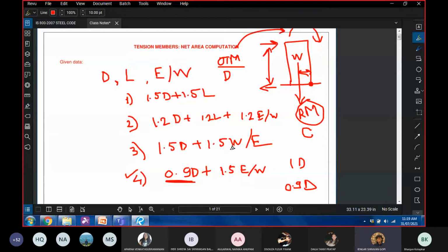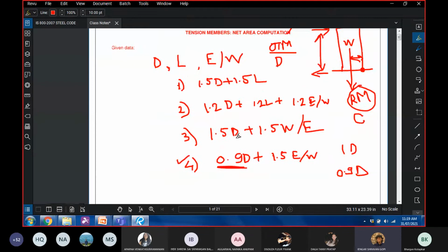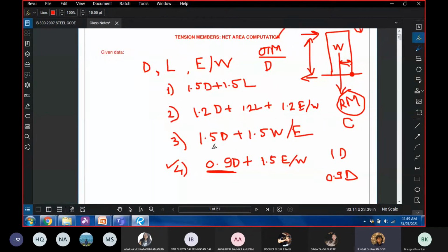So basically, here we just calculate the worst case scenario that a building is going to realistically face and then use that as the partial safety factor. And when I say worst case scenario, I don't mean that God intends the building to fall and there are all kinds of loads at once, but the most likely loads it will face and the worst those loads will get. So while designing the buildings, we design the member for the worst of all this.